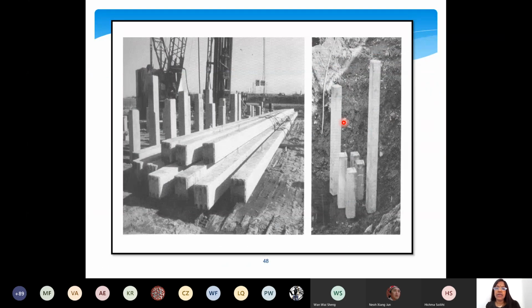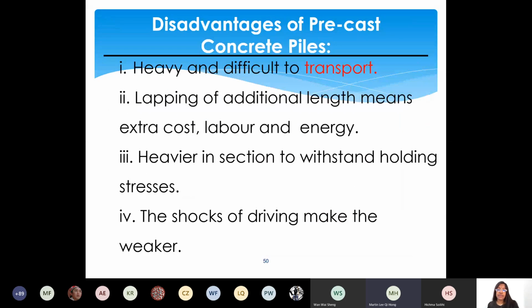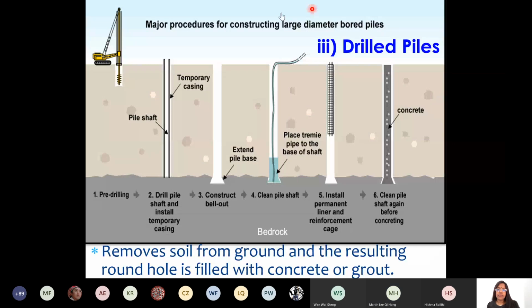You can see here the different types. Yes, how do they clean the shaft? How do they clean the shaft before putting the concrete? Clean by pumping water. Pour the water and suck it out. Use the centrifugal pump to lift the water after cleaning. It's all by motor and pump. See, the hose is put inside. Supply the water, it cleans,